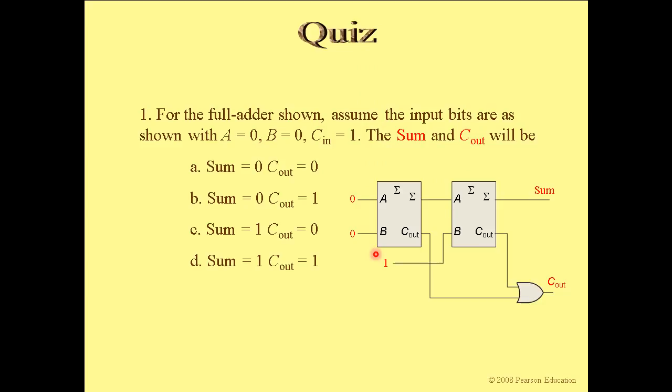Now, in the next couple of slides, we try to do a little bit of math to see whether we understand it properly. So what I did is I have drawn a full adder at the right side. I'm still using 2 half adders, combining an OR gate and a sum. Okay, and plugging in all the numbers that we are given in the question.